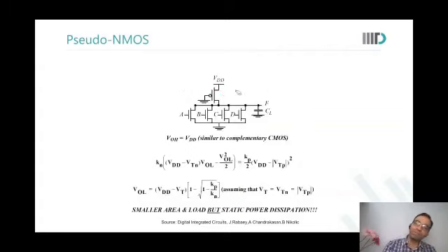So, are you able to see this? Not exactly, sir. I mean, why is VOL changing here? Okay. So let us say the PMOS resistance is 10K. And NMOS resistance, let us say each of these NMOSs has resistance 2K. So when all four of my NMOSs are on, what is the effective NMOS resistance? 2K by 4, 500 ohms.